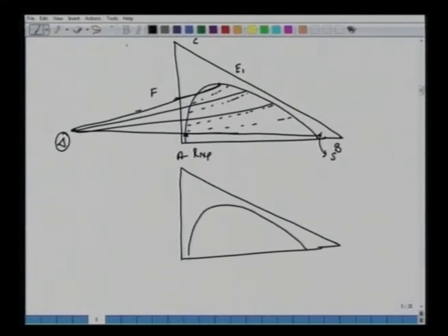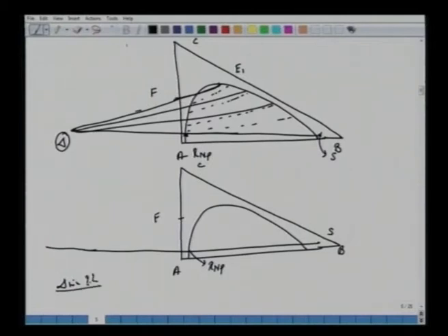So all we do, we find that tie line in this case, which if we extend will intersect the line here. So you can say that now we have the amount of solvent corresponding to this del min, which will give us an infinite number of stages, because now this is the same operating line which is now coinciding with this tie line. All right. So there are several such tie lines. First, we should find that first tie line, which if we extend, intersects the line connecting between R and P and S to give us del R min.